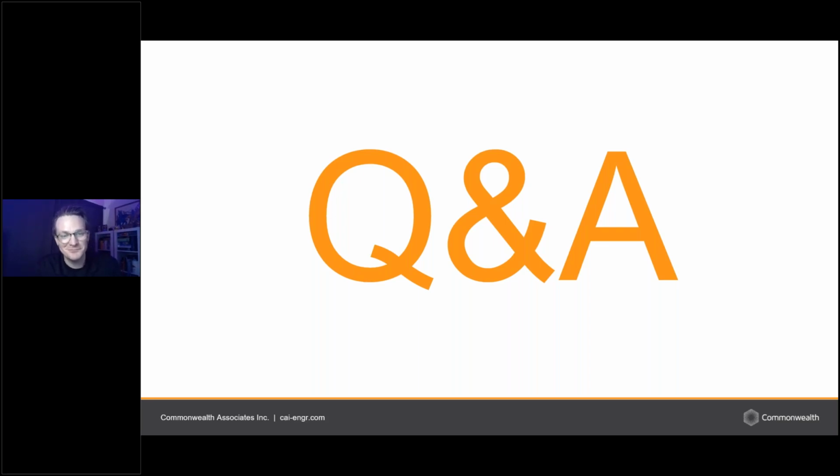Yes, I have. In one case, it was actually a surprise to the field crew that showed up that day, which was rather interesting. But once we got through the concept of 61850 and what it was and went through the documentation with them, the feedback at the very end was that they liked it because it was a lot less labor intensive. You're not moving around wires, you're not having to do certain circuit continuity testing. It's done digitally. So they actually came to really like the simplicity of commissioning with 61850.